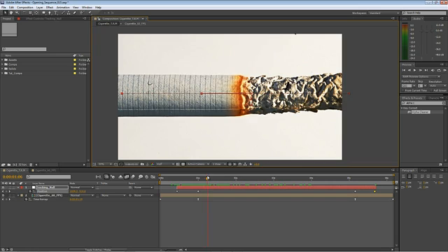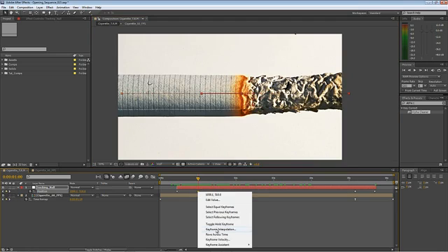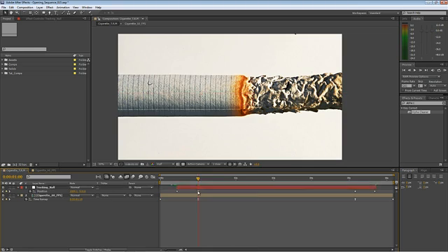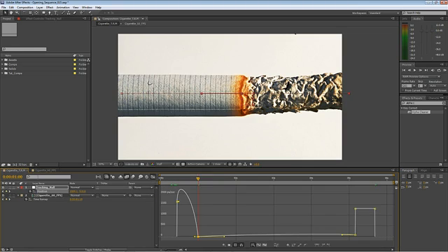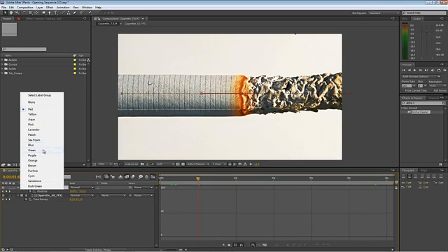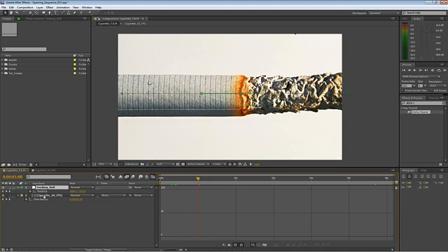So let's see, we've adjusted the tracking data a bit and it's working good. We need to set this keyframe to easy ease, since I can see it's going to graph mode. Actually, it's hard to see because of the coloring. Let's set the tracking data color to green. Yeah, this is a pretty decent track.